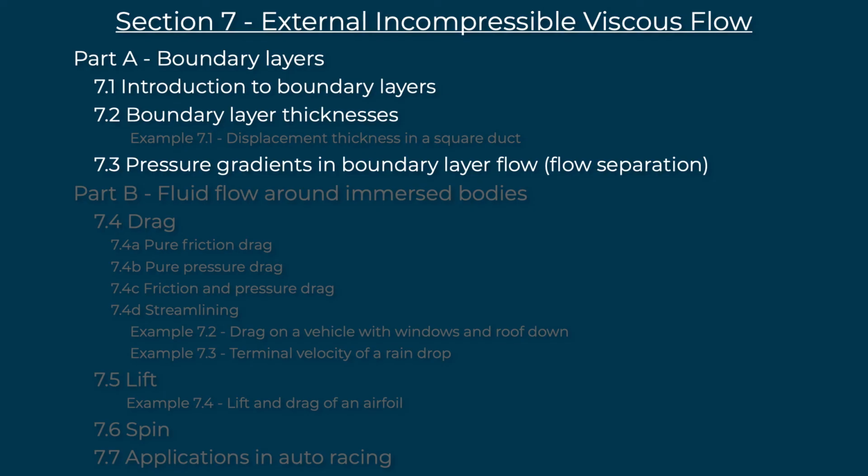So a strategy if you wanted to delay your separation is to have a turbulent flow instead of a laminar flow. And we saw a nice example video of an airfoil there that showed many of the important features of these boundary layers. And in general, separation means when the flow is not attached, so there's no flow right against your surface anymore, so we don't get those forces. That leads to very catastrophic things like stall on wings, for example. And we'll see in the next few videos as we go through to part B, also a big impact on drag. So that's why it's important to have strategies to know if we could sort of delay that or not.